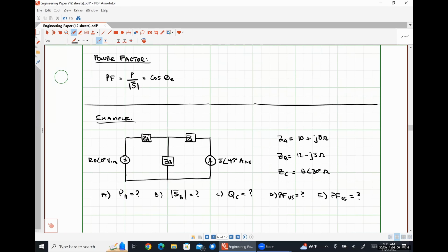So I want to reiterate, I genuinely expect you guys to not memorize literally any of the equations that I've hit you with today. We are simply going to use the complex power fundamental relationship: S is equal to the RMS phasor voltage times the complex conjugate of the RMS phasor current to figure out damn near everything here, okay?